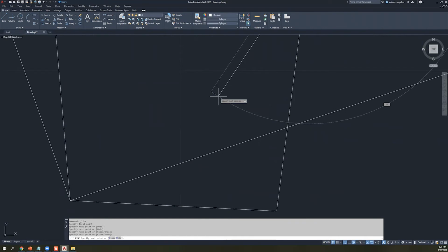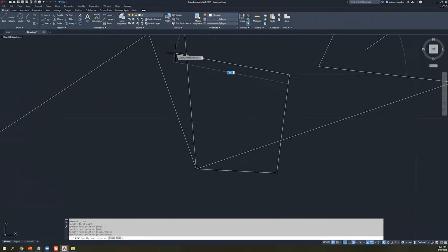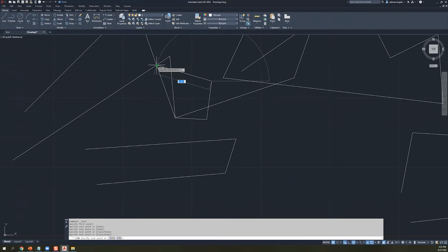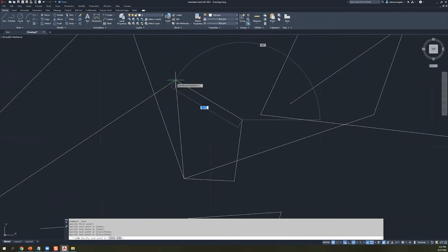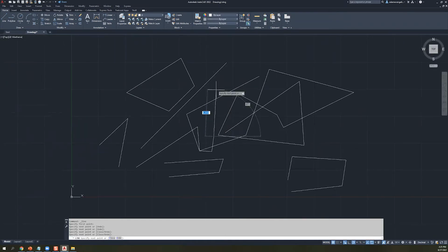And so what you're seeing is those green points are something called object snaps, which essentially just snap your cursor to a particular point of interest, whether that point of interest is an endpoint, whether it's an intersection point or something like that, or perhaps it's just an extension of another line or a horizontal. There's all sorts of stuff like that that could help orient your next click essentially, right? And so this is literally just extra geometrical information about your drawing that you're taking advantage of over here, right?